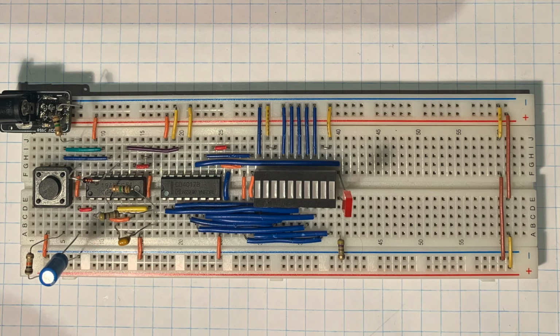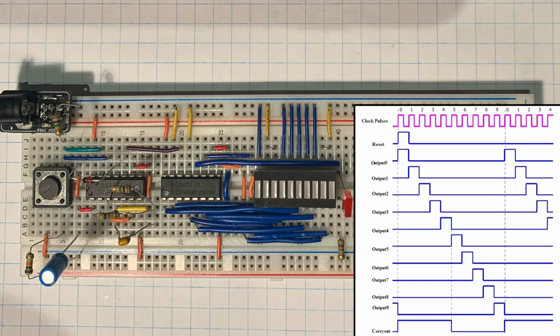This is the decade counter build, which adds a 4017 chip to the NAND gate oscillator. The clock signal is inputted into the clock input of the 4017 chip. This chip creates the effect of a ring counter, where for each high-low cycle the clock signal inputs, it creates a high for one of the 10 outputs at a time. This process goes all the way around the chip, giving a ring effect.